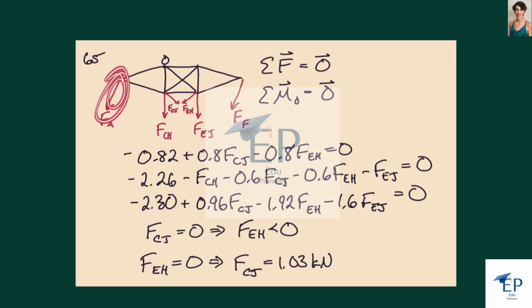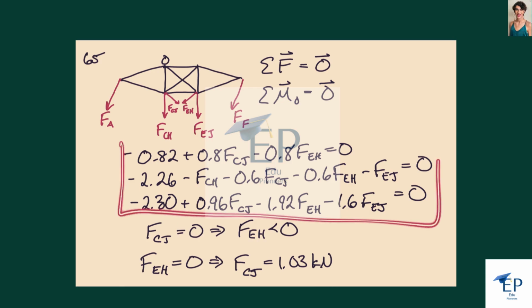These are the external loads acting from the transmission lines, and the internal loads here from where we cut across the structure. And we can sum the forces and then sum the moments, and I picked this as my origin here. And again, I can write these as vectors, just like we did in all the previous problems. And we wind up with these three equations if we sum the forces and sum the moments.